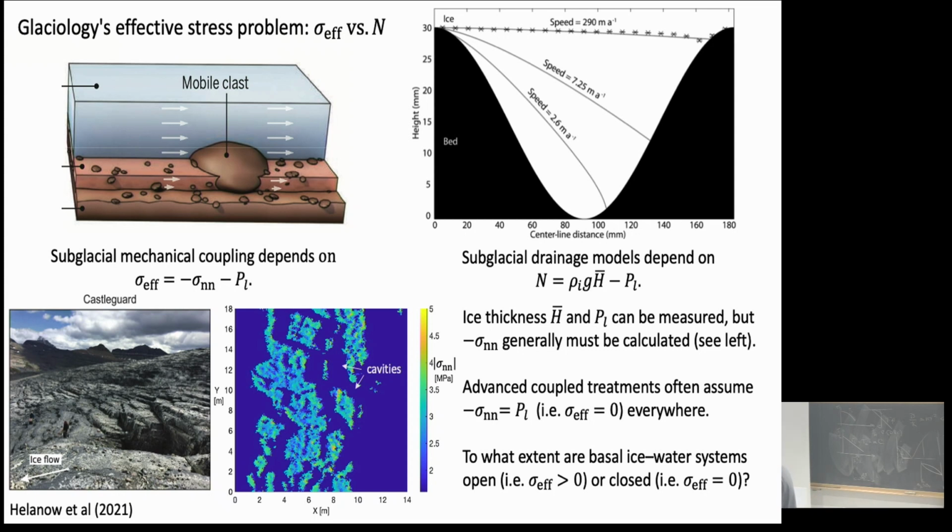And so this is an image of the normal stress on the bed over a bed that's formed in this way. You'll notice that the dimensions are tiny. So a lot of work goes into the numerics on this problem. But the cavities are everywhere that's the dark blue, this level, because that was the applied water pressure, which was assumed to be equal everywhere along here. And there are regions where the ice is contacting the bed, and that has to support all of the weight of the ice above and all of the basal shear resistance as well.